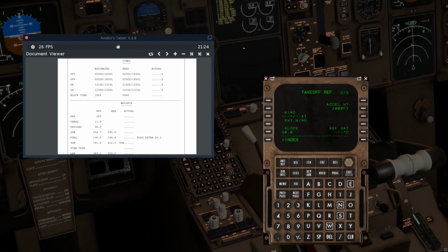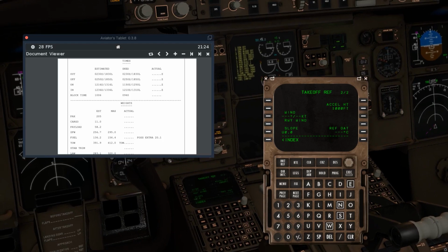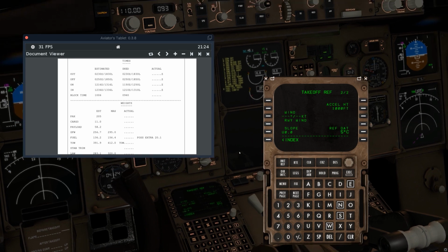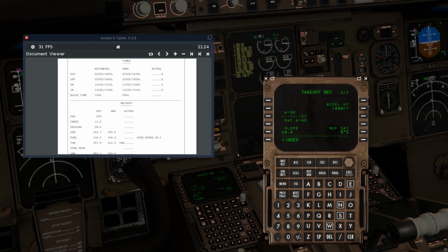Okay, our outside air temperature right now is 5 degrees. Let's see if it likes that. All right, 5 degrees. And our wind, I don't know what our wind is. We don't really need it, but if you have your wind data, if you listen to ATIS, you can pull it straight from there, punch this in, as well as the runway slope. If it has that, you can enter that in. Next, we will move to the pre-flight route.